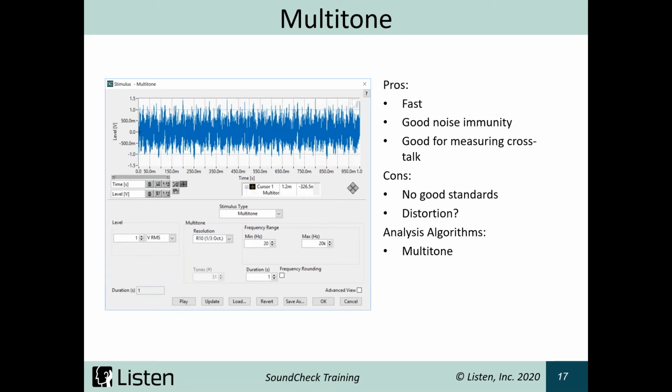And the distortion can be a little bit trickier. We can get distortion out of it, there are options for that, but we can't get harmonic distortion. Since we're playing all these frequencies at the same time, we don't know if the 200 hertz playing is the harmonic caused by 100 hertz, or if it's just the fundamental of 200 hertz. So without being able to filter all of those out and find out what is causing what, the distortion we can get is a little bit different.